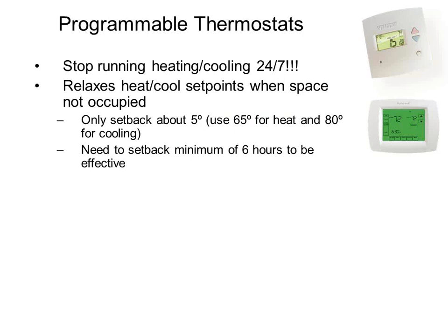Two things happen though. One, when you come out of setback, it usually forces you to go into more stages of heating and cooling capacity, which is not necessarily the most efficient way to run your unit, so we don't always want to do that. And the other thing is that all the surface temperatures in your building are, let's say in the wintertime, really cold, and if I set back a lot, yeah, I recover and I heat up the air, but my surfaces are still cold for a while. So I don't like to get too aggressive with the setback.